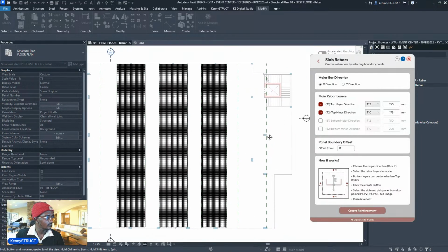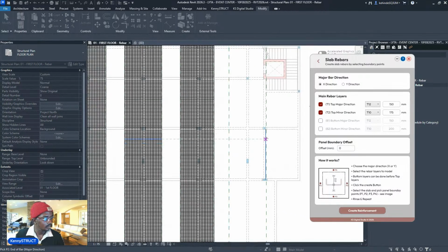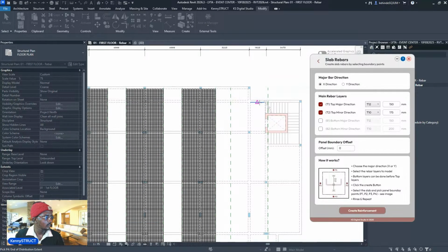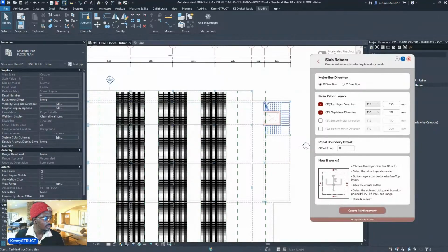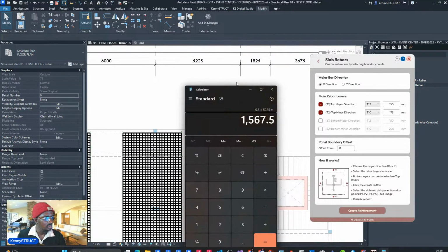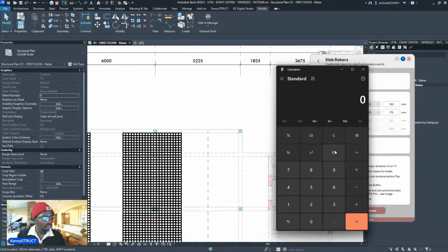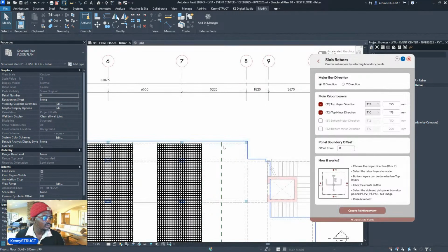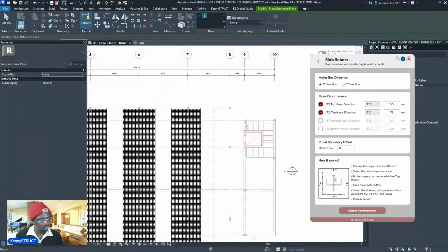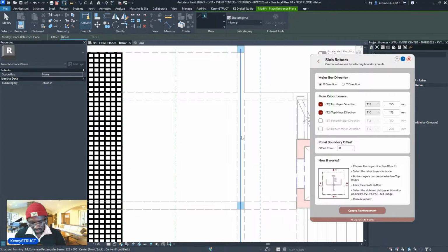So we can do the same thing here. Oh, okay, sorry. This should not be this span. This should be 1/3 of this, I guess. 0.3 times 1,825. It's about 600. Let's say 550, 600. So we're gonna do that same thing here. 600 offsets from the center of the beam and do this here.